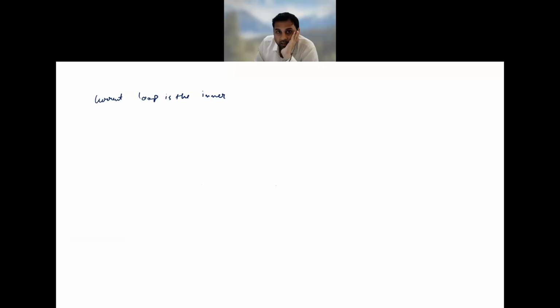Whatever be the case, we have a frequency variation of either 50 hertz or 100 hertz. Let's say if you are doing a boost PFC, it will be 100 hertz, and we want to track that 100 hertz component. At the same time, we want to reject the high frequency component, because in the current you also have a high frequency current coming in, because you are doing average current control.